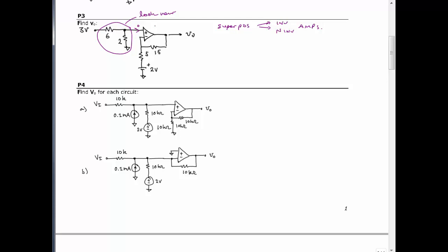That's because, again, there is 0 current flowing into the OpAmp non-inverting input. So it's as if this circuit here is completely detached, I'm going to put that in quotes, but it's detached from the OpAmp. Effectively, it's detached.